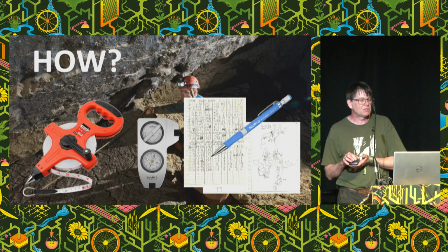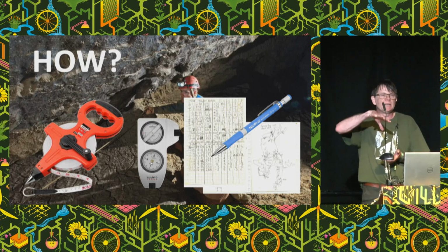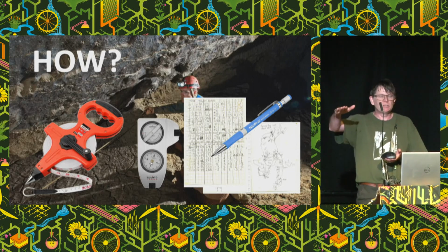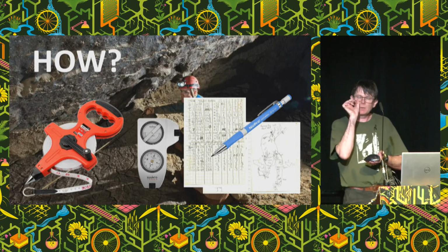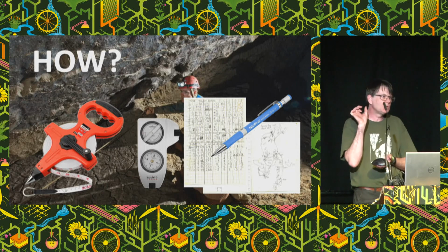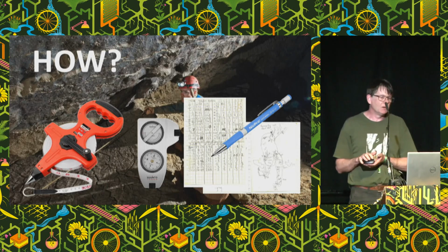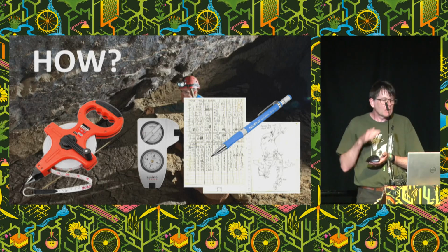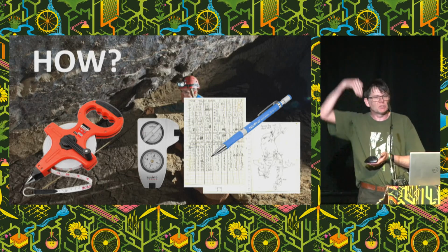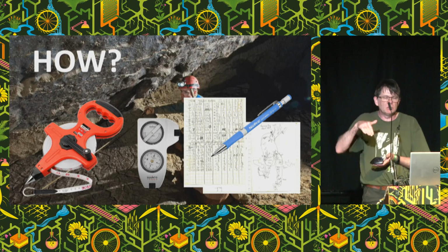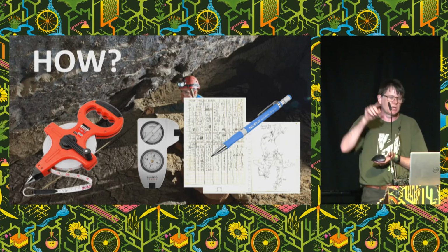So in this device you see in the middle, the bottom dial is a compass, so when it's held horizontally, it's a sighting compass. You look through a window to read the scale, and so you can measure bearings accurate to about half a degree, and then the clinometer works by measuring essentially which way's down, so you know how steep, and you sight from station to station.